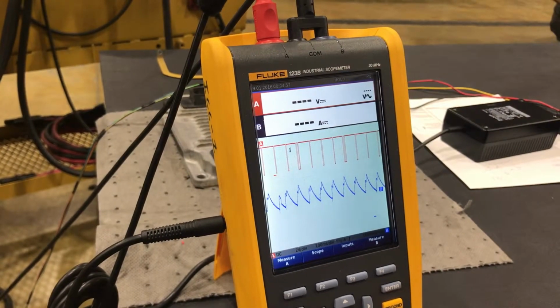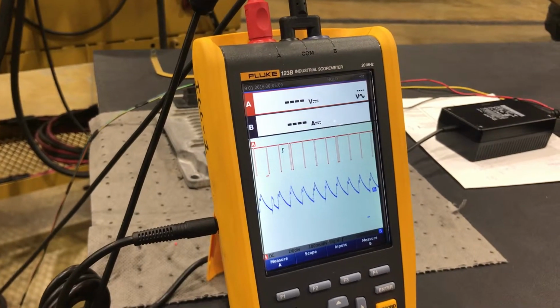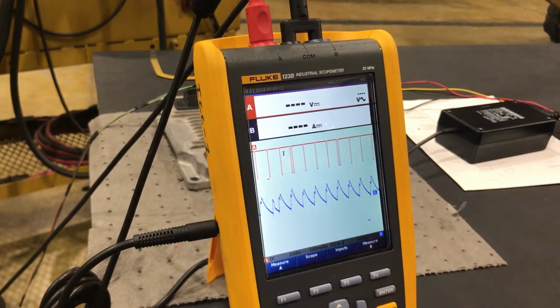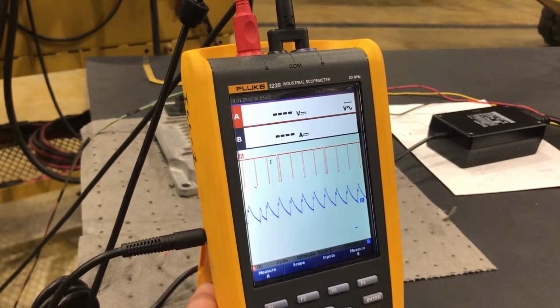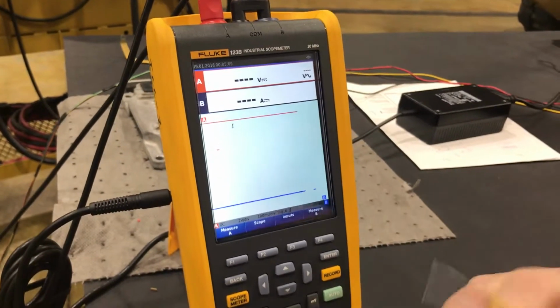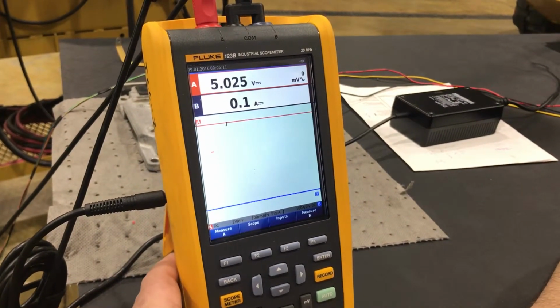As we've been talking, they've set up and pulled the number 1 glow plug out of this engine. So we'll go ahead and run it and look at that again, and then I'll show you how the firing order works. So we'll go to run, and when we get a good pattern, I'll hold it. Go ahead and crank it.